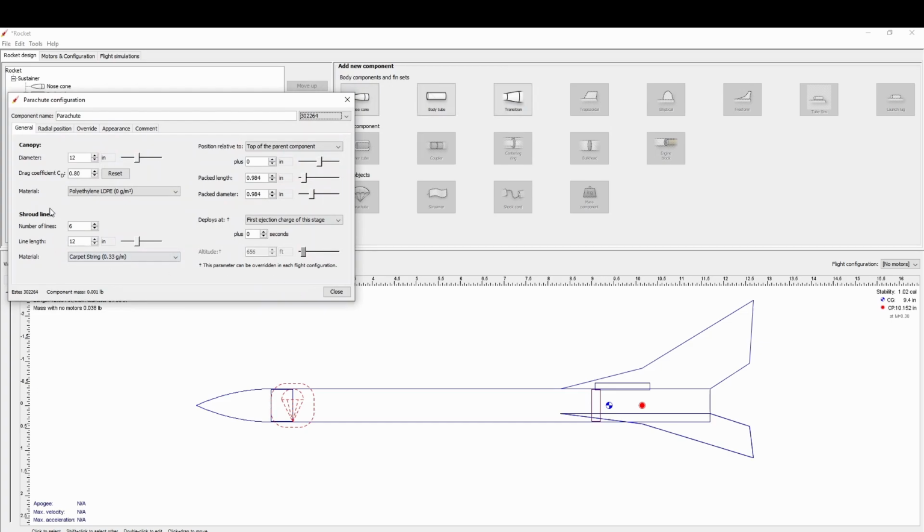Okay. The only thing we don't like about it is how big it is compared to the rocket. The only thing you're really concerned about here is how much it weighs and how far away from the center of gravity it is. So what it looks like is not really all that important. When you wrap this thing up, it's around 2 inches, and we'll keep it around 0.7 so it'll fit in the tube. And then we'll slide it down because this is the shoulder, so we obviously don't want it there.